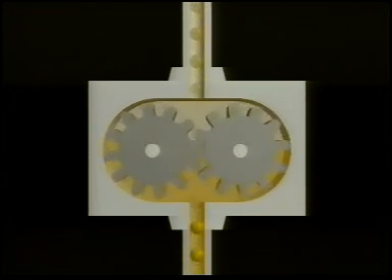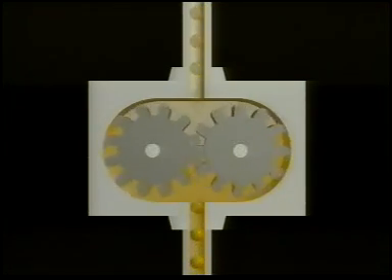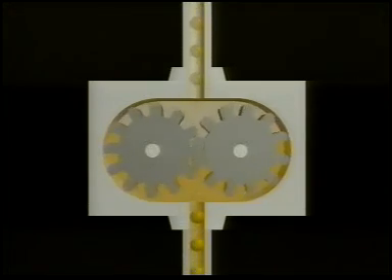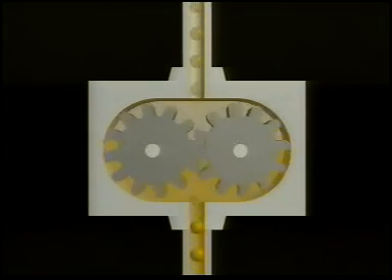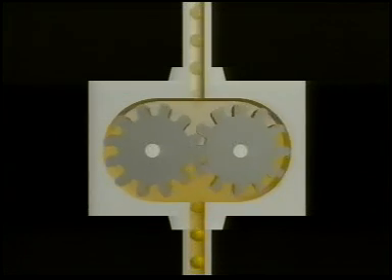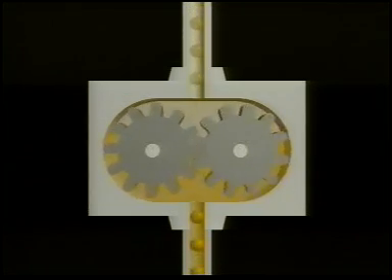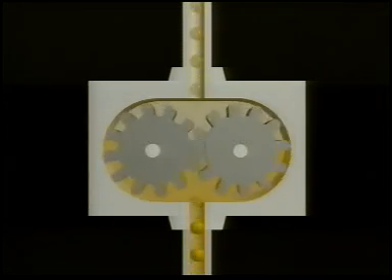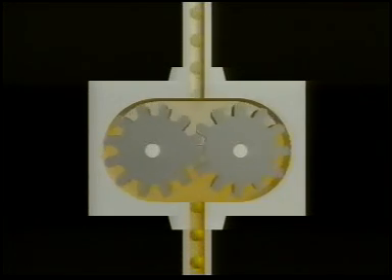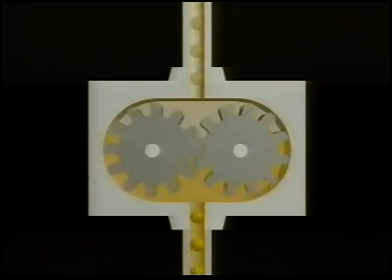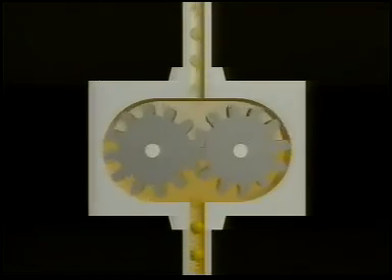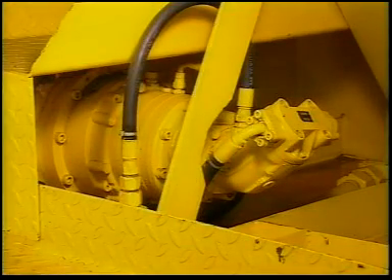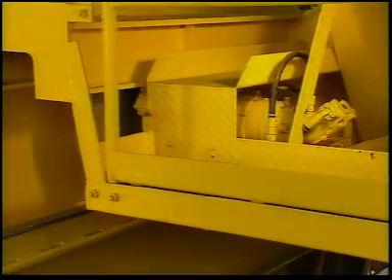This is the quantity of oil that the motor can take in one revolution. Rotational speed N is calculated from flow rate divided by consumed volume. Any calculations of hydraulic systems must always make allowances for leakage oil loss. This hydraulic motor, which drives the trolley of a gantry crane, converts hydraulic energy into mechanical energy in the form of rotary motion.